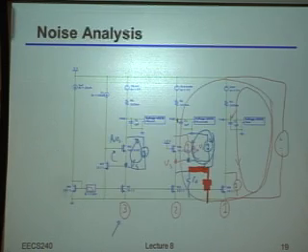What about the noise from this guy? Yeah, that's what I was mentioning before: largely speaking it gets filtered, because we had to put a cap there to make that the dominant pole of the whole feedback loop. If it wasn't the dominant pole, we would have had stability problems and it would be really hard to make this whole thing work in the first place. So just to repeat for the online audience, the question was, what about the noise of that device? I was reiterating that I typically have to put a capacitor there anyway to make that the dominant pole, and therefore that noise also tends not to be a dominant overall effect.